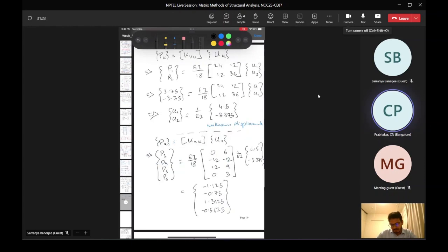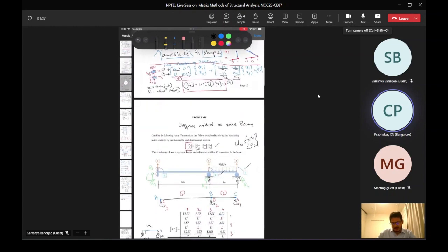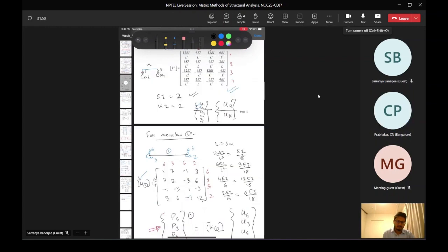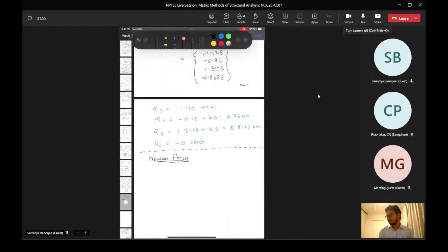I mean, for the methodology, we have to use these elements as well. Yes, exactly. Like we already know all the reaction forces, we know the different distribution. Now you can directly find the bending moment. If we are writing some program, then it is understood: we can bring this stiffness matrix and find the member end forces. If we are doing it manually, we can directly use the equations. Exactly, from strength of materials class or structural analysis one class also.